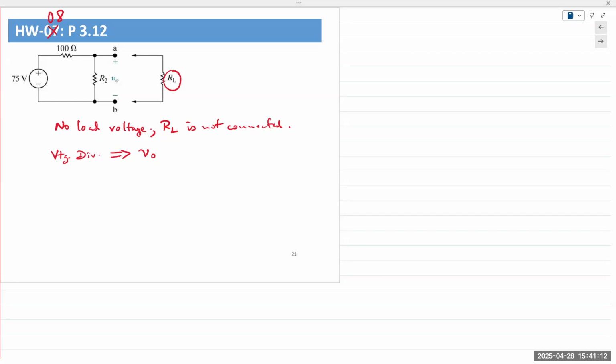Right? We are required to teach you certain topics and then required to assess your knowledge of those topics. So voltage division and current division. Do not skip. So you find VO from voltage division. Then you connect RL. And now they're asking you to find either the value of RL or trying to find VO again.